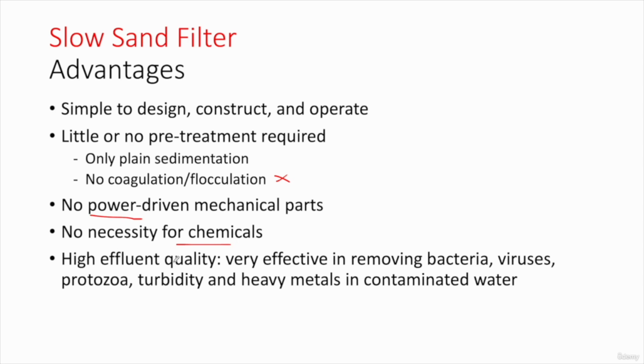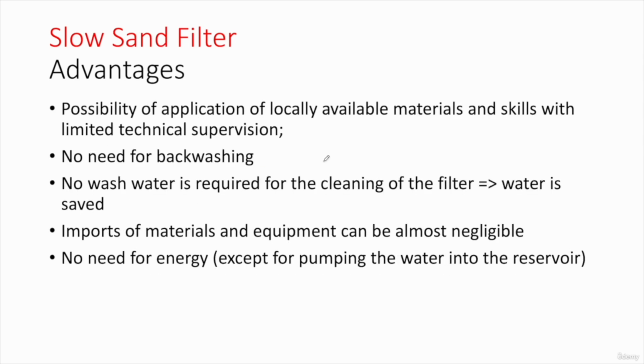And we have a high effluent quality, since we are able to remove many types of bacteria, viruses, protozoa, and also reduce the turbidity and the heavy metals. There is also a possibility of application of locally available materials, since we need basic materials and also basic skills with limited technical supervision. We don't really need engineers or highly skilled and experienced operators. No need for backwashing. No wash water is required. Thus, water is saved. We are not throwing any kind of water. Imports of materials and equipment can be almost negligible.